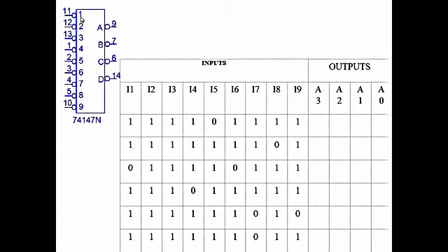And what we have here is 1 through 9 going on the inputs, but you'll notice something. They all have bubbles underneath them. All the bubbles going on the inputs. Bubbles mean an inversion of some kind. There's an inverter there. So basically we're saying that these are active low inputs. In other words, it takes a low to activate those inputs. Same thing for the outputs. The output's actually inverted when you do your binary number. So the binary number is 1, 2, 4, and 8, just like we have been doing. It's just a binary number.